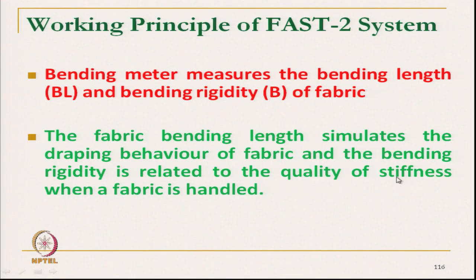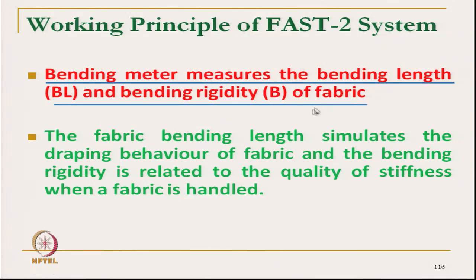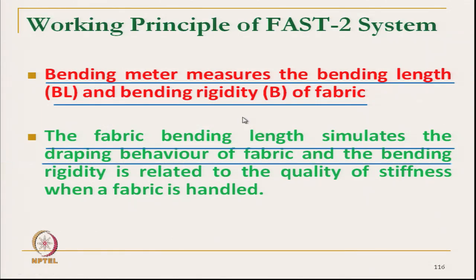Now, the next module is phase 2, which is the bending meter. It is exactly similar to the Shirley bending tester, and we get similar characteristics here, bending length and bending rigidity. The measuring principle is exactly the same as the Shirley bending tester. Fabric bending length simulates the draping behavior. So, from the bending length value we get an idea about the draping behavior, and also bending rigidity.